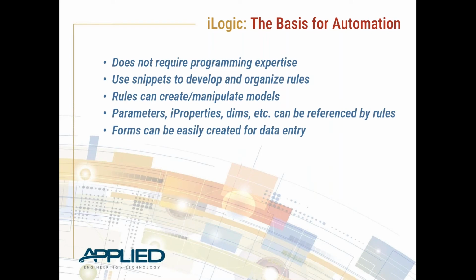As far as locally, you can automate your designs locally using a built-in portion of Inventor, in this case called iLogic. You do not need any programming expertise. It is beneficial if you do have it. You can create more in-depth rules and things of that nature when you're in your Inventor iLogic rules. Inventor comes with what's called snippets. So it's a starting point for you to develop your various rules within your parts and assemblies.